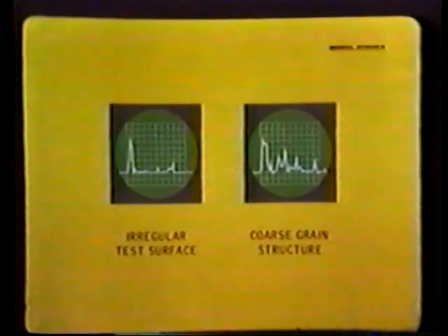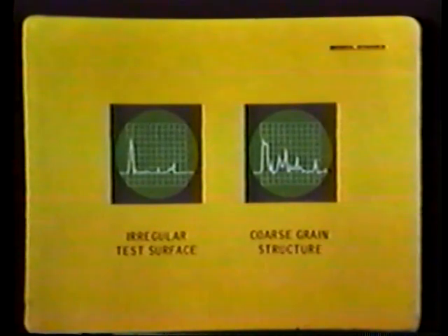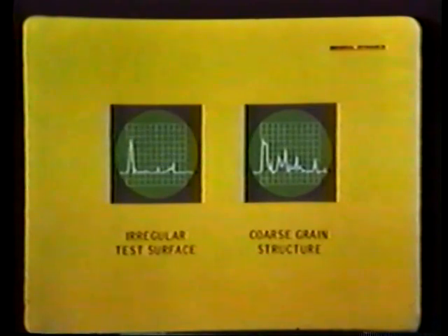Sometimes a poor response can be improved by experimenting with different incident beam angles, or by lowering the test frequency. But in lowering the test frequency, you should also remember there is a corresponding loss in sensitivity and resolution.